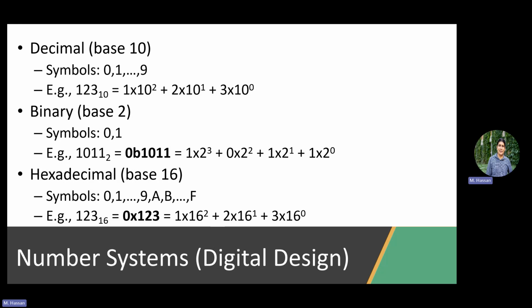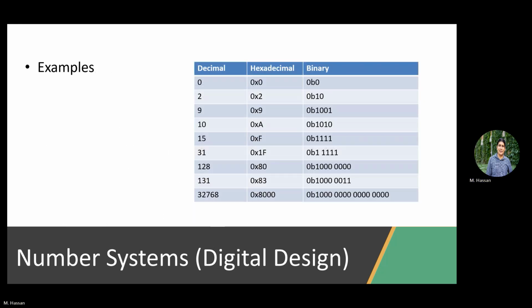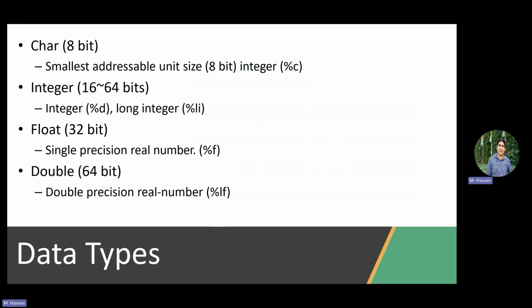Some of the things we said: I need low-level hardware control, which means I need to access certain bits and certain registers. So you need to review how we handle things. As an embedded systems engineer, you need to be aware of numbering systems, mainly binary. You need to access particular bits. We use bitwise manipulation a lot in embedded to control certain bits in a register through masking. I only have these slides so that you have them when you study, to refresh your mind about numbering systems, data types, and all that.